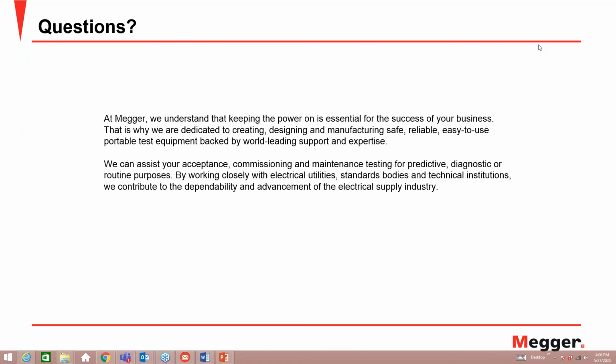All right, thanks, Sanket. Andy, the new station battery systems I'm seeing installed have more and more insulation around the posts and straps. What does Megger offer to enable measurements to be taken with the new setups? Okay, we are seeing some battery manufacturers doing this basically for safety concerns. You'll see caps that may only have a small access port in them. And we actually offer adapters that will go through those access ports, so you can take those measurements.